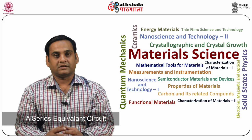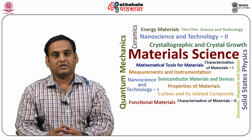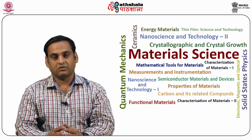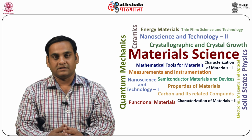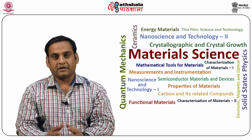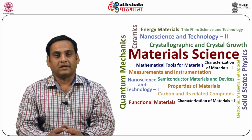A series equivalent circuit. A capacitance Cs in series with a resistance Rs has a series impedance Zs, which is equal to Rs plus 1 over j omega Cs. The impedance of the capacitor with the real dielectric is Z equals 1 by j omega C0 times epsilon prime minus j epsilon double prime, where C0 is the capacitance without the dielectric.